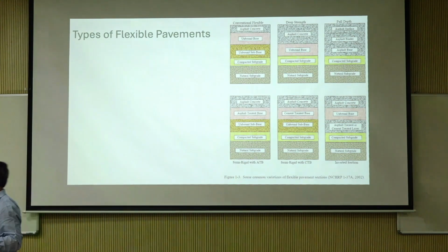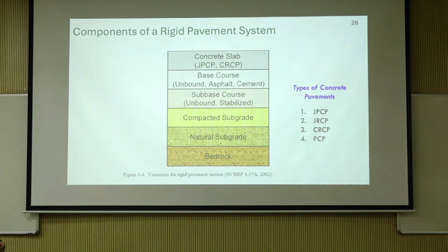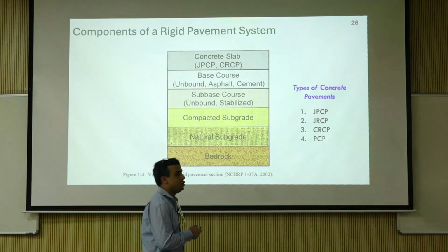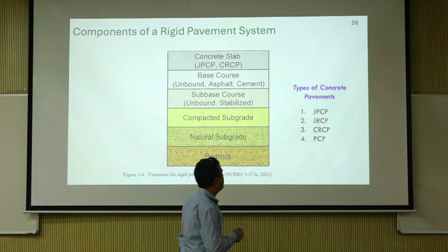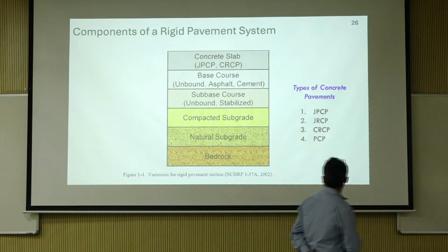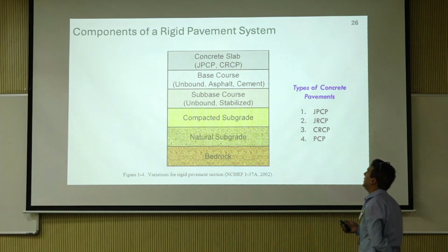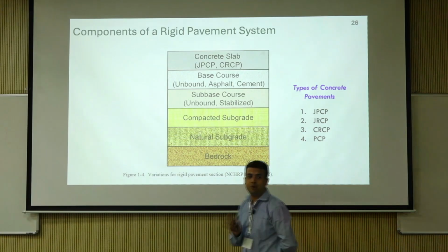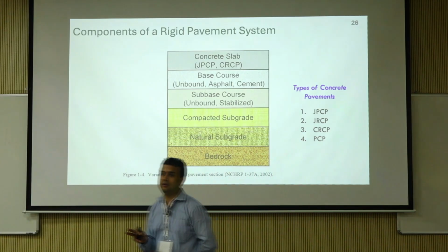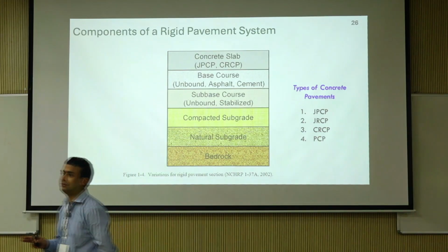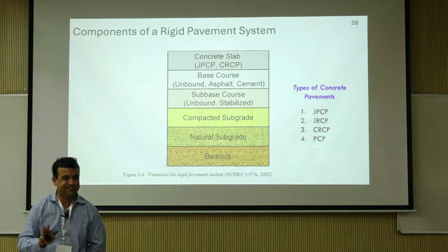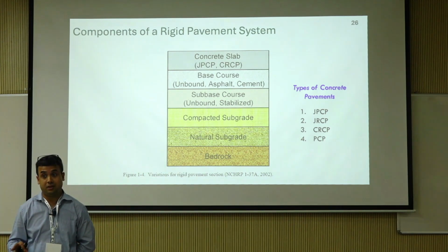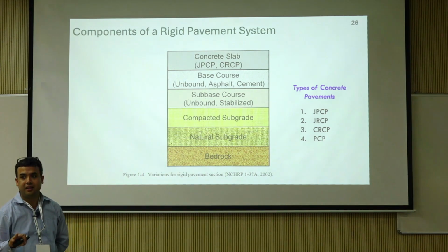This is just, again, background information for you all to keep on top of things. Rigid pavements: JPCP, jointed plain concrete pavement, CRCP, continuously reinforced concrete pavement, and stuff like that. Again, as I said, rigid pavement is a little more forgiving of your mistakes on the underlying layers. Erosion is a big issue, pumping is a big issue, strength you can get by.